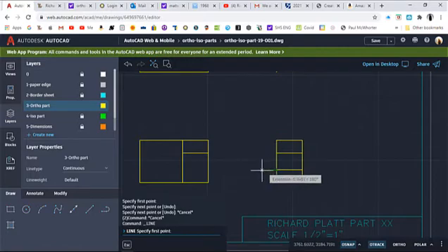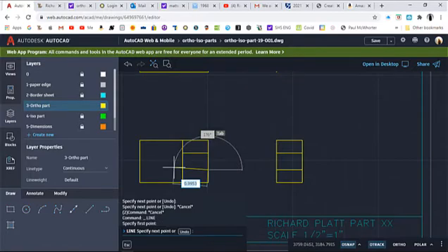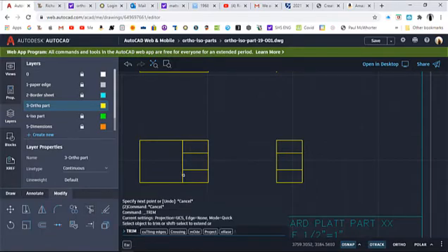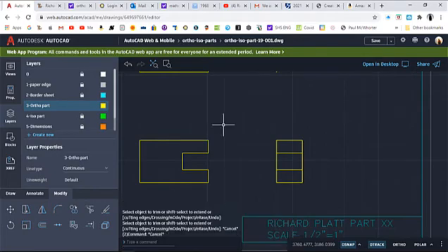I'll come over here and do the same thing. I'll reference off him and let it track over to this edge, and I'm going to run over here and draw, let it intersect right there. Hit escape, get our good buddy the trim command over here on the modify menu. Okay, get rid of some of these lines, get rid of that, get rid of this. This we're not going to change because that's what we want. So let's hit escape. We're out of that.